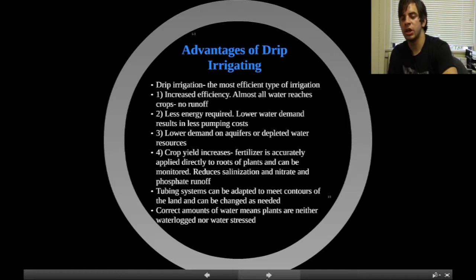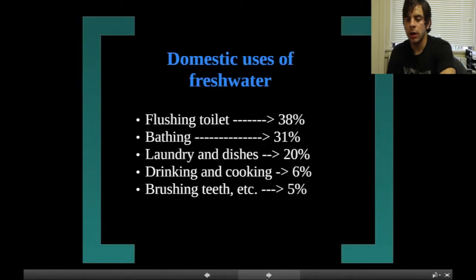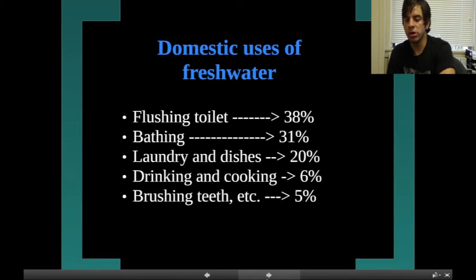Surface and groundwater issues. Surface water infiltrates and percolates through the soil into aquifers. Aquifers are layers of porous rock, sand, and gravel, where water is trapped above a non-porous layer or bedrock. Recharge zone, surface area in which water infiltrates into the aquifer.